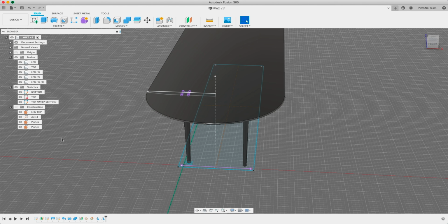One quick modification here. If we go to the bottom again, we're going to move these table legs a little bit closer to the side. We could say they're 1.5. And I actually want to reference this other one so that I don't have to change these every time. So if I have this one selected, I showed this before, click here, and now we're referencing D12. You'll see that it's labeled FX. So that means anytime I change this one, both of them change.